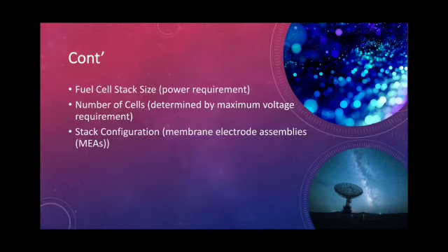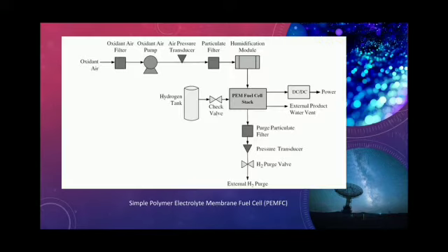For a better fuel cell, the fuel cell stack size must be considered for the power requirement, and then the number of cells to determine the maximum voltage that is required, and then the stack configuration. This is the simple polymer electrolyte membrane fuel cell.